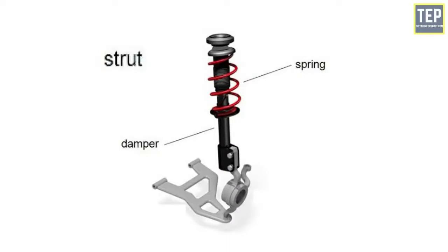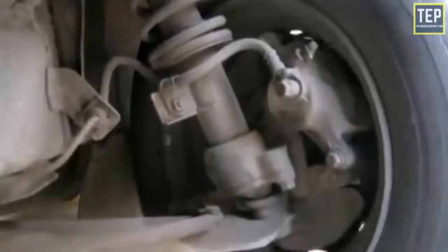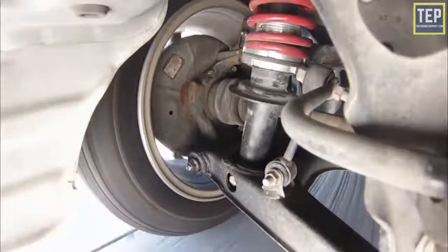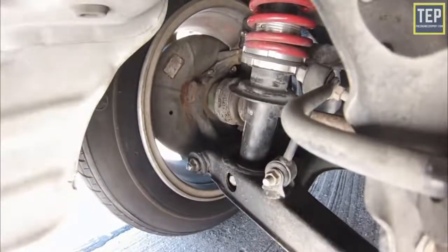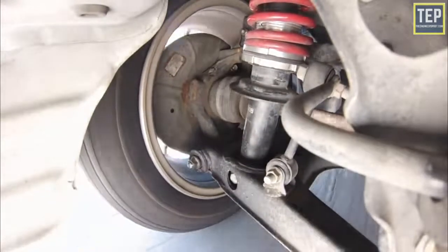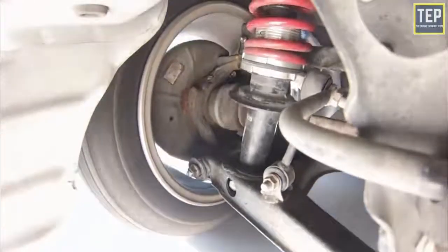When the vehicle comes in contact with the irregularities of the road, the wheel moves up and down on the radius of the lower link. Due to this motion, all the shock is transferred to the strut, which absorbs the maximum amount of force. It has relatively simple construction, which results in a compact and cheap design.